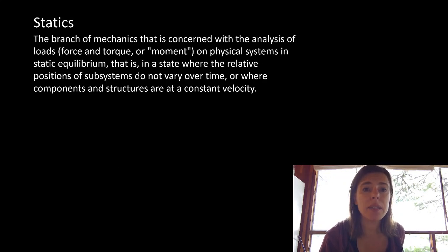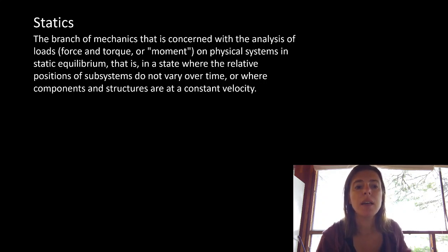So statics, which is what we want everything to be. Statics is basically the art of staying still. We do not want our things to move. So statics is the branch of mechanics that is concerned with the analysis of loads, so that could be force or torque or moment, on a physical system, so our object, in static equilibrium. So we don't want it to move, and we want to know what all those forces that are applied are doing internally to our object.